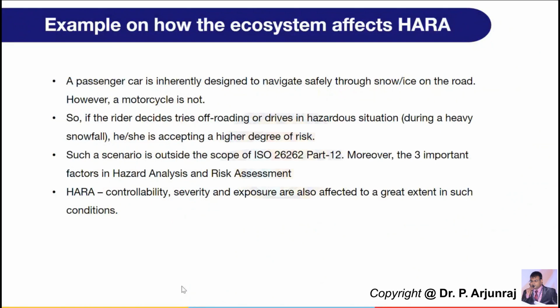What I was telling, the examples are all related to mechanical, but when it comes to electrical and electronic aspects, we also need to give some safety features. In case one circuit fails, you also need to go for a second circuit. Like in the case of brake application, you have the hydraulic brake system even for a two-wheeler. In the case of four-wheeler application, you have a dual circuit, right? So if one circuit fails, the other circuit gives you the chance to stop the vehicle.